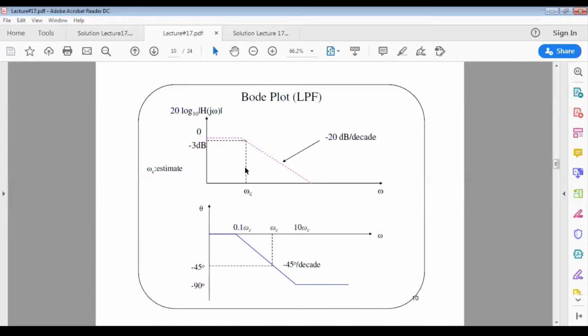Okay, and the cutoff frequencies can be obtained by simply projecting the frequencies value, or by simply projecting the amplitude which is 3 dB lower than the passband amplitude. Then we can have the frequencies. For instance, if your amplitude plot is 0 dB, okay, so 3 dB lower will be the location of your cutoff frequencies. So by projecting a 3 dB or negative 3 dB value of the amplitude, we can then obtain the cutoff frequencies.